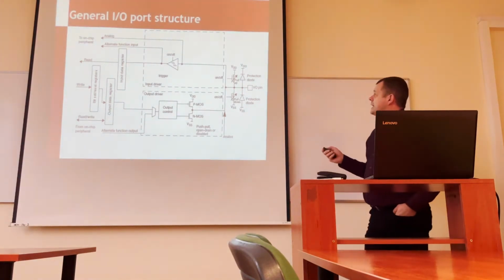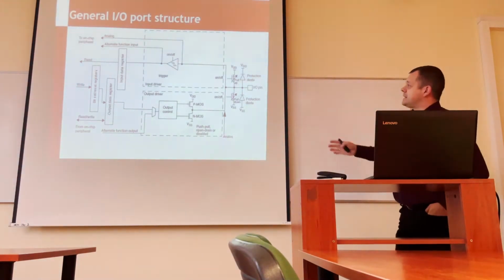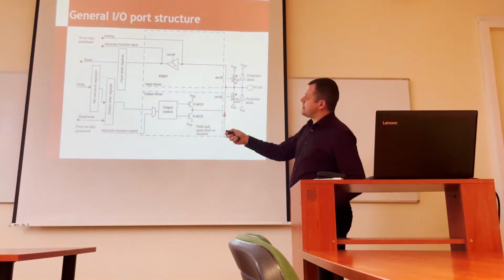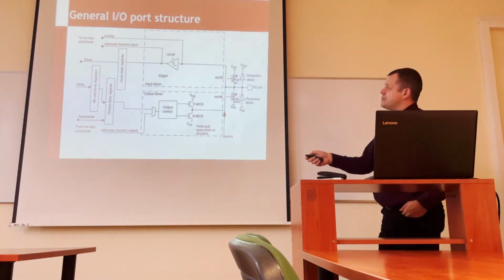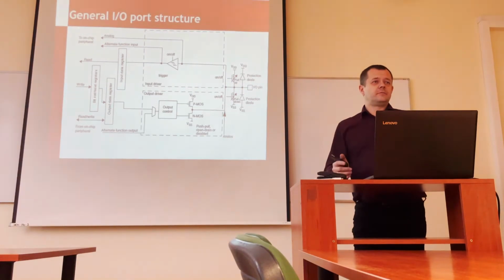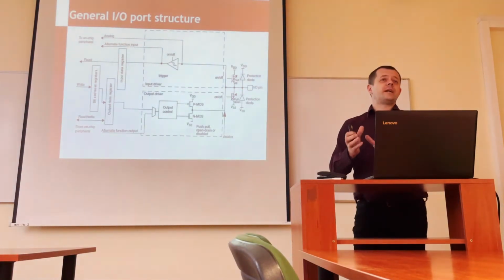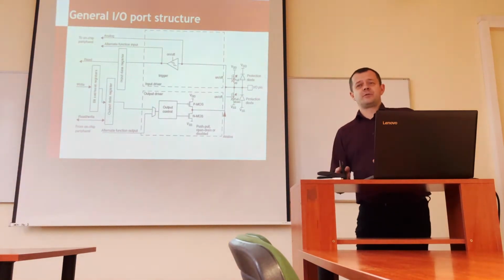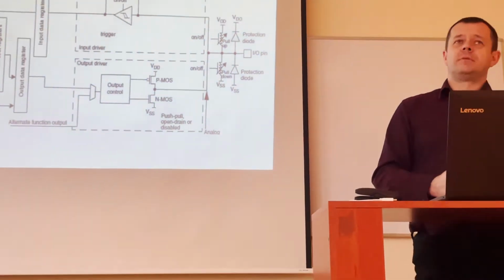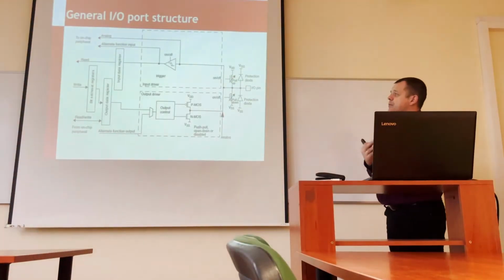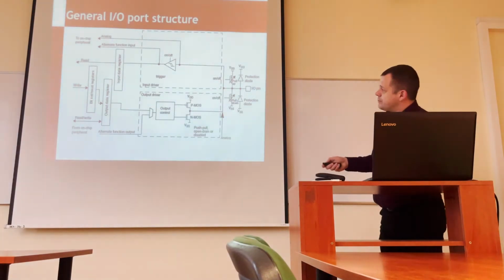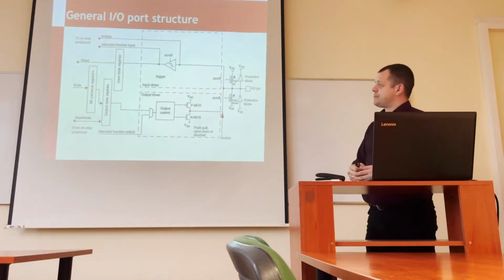So first of all, in the case of the I/O pin, here is the hardware, the physical pin, and here are the internals of the microcontroller, so various registers, because the port is generally a peripheral. If you take a look from the microcontroller's point of view, there is a microprocessor and a port. A port is usually a peripheral with dedicated registers, dedicated functionality, and dedicated behavior. So from the microcontroller's point of view, we've got a couple of registers.